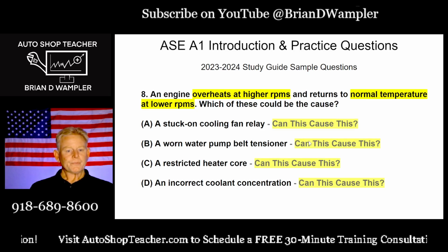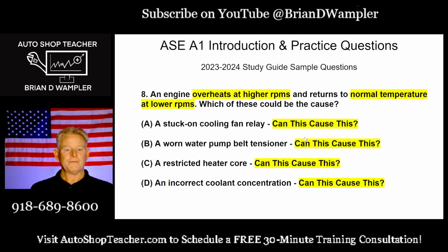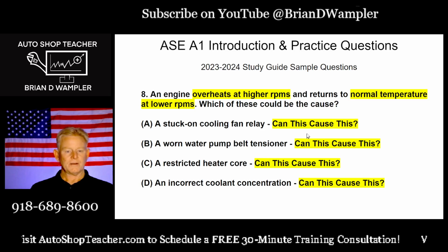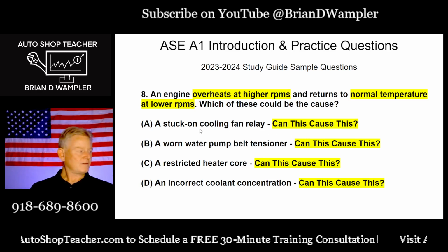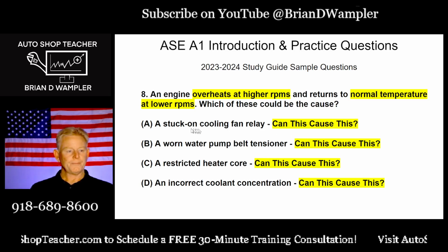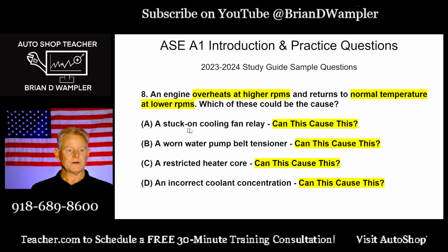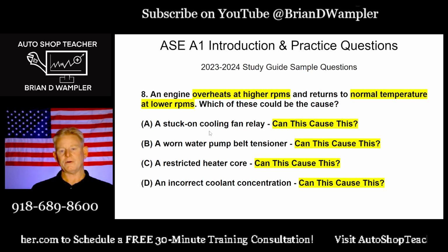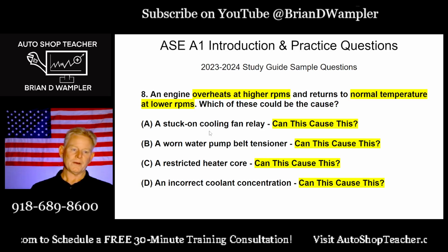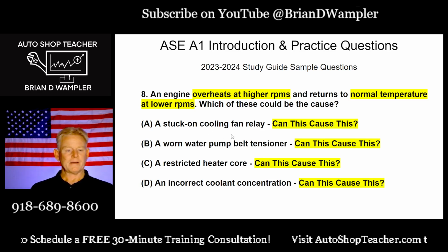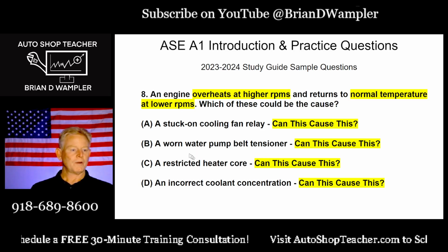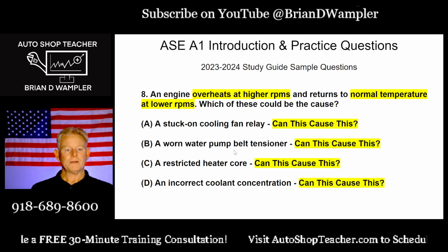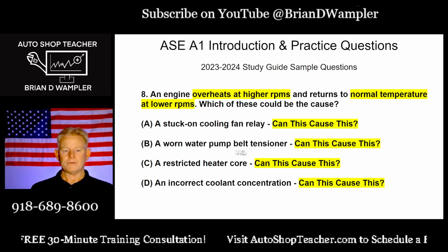So, continuing on. Can the cooling fan relay cause this? Well, if it says it was faulty, possibly, but this says stuck on, meaning the fan's running all the time. I think not. What about a worn water pump belt tensioner?